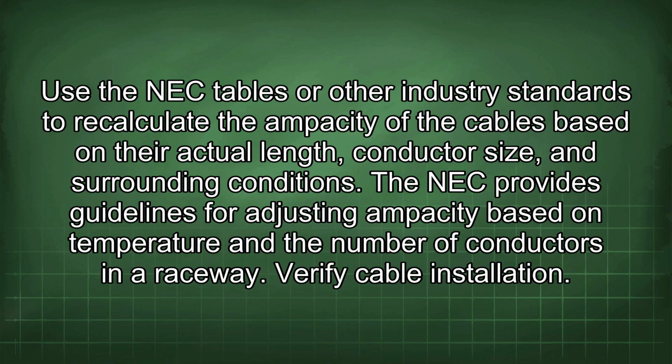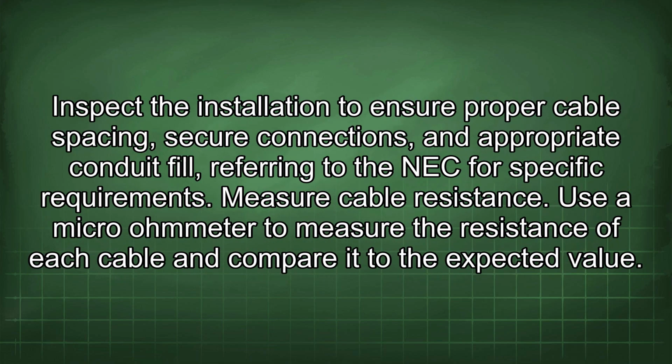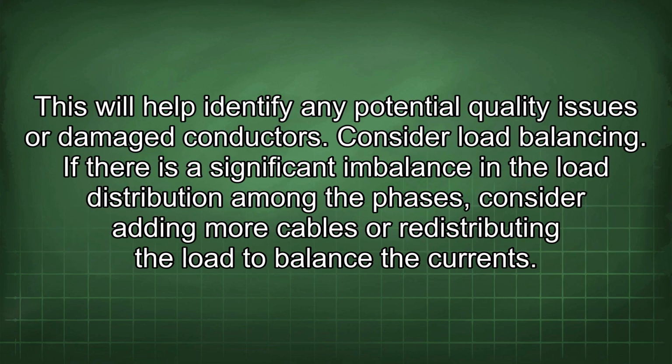Verify cable installation. Inspect the installation to ensure proper cable spacing, secure connections, and appropriate conduit fill, referring to the NEC for specific requirements. Measure cable resistance. Use a micro-ohmmeter to measure the resistance of each cable and compare it to the expected value. This will help identify any potential quality issues or damaged conductors.